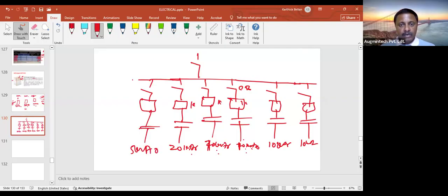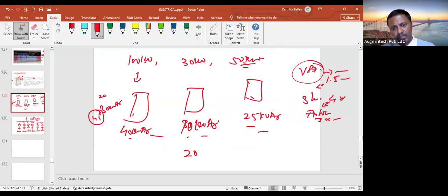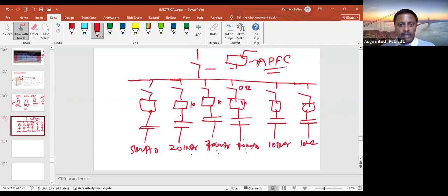So for all these three motors, I'm going to enclose them in a single capacitor bank, Mr. Tony, Mr. Morosi, right? In that case, whatever the reactive power is, there would be a relay. We call this the power factor relay, the automatic APFC panel, automatic power factor correction relay. This relay is going to sense the reactive power and then feed it to the circuit. Depending upon the reactive power, if any of the motors has started, or if you start all the motors together, also not an issue. We have an automatic operation.